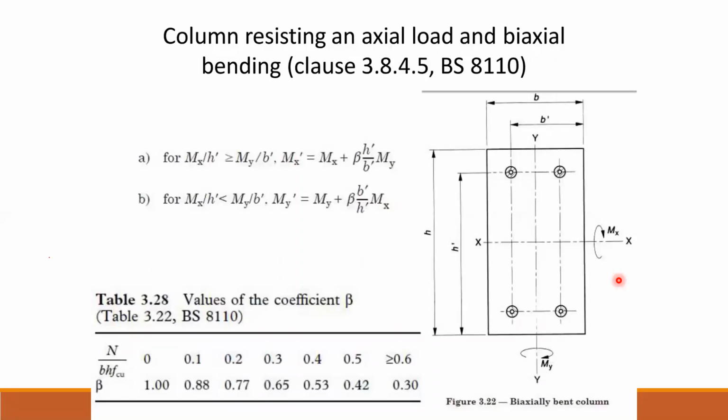Column resistance to axial load and biaxial bending moment. Up to now we have discussed the axial load and the uniaxial bending moment. Hereafter we are going to discuss the biaxial bending moment. For Mx over h', everything is given. Mx is the moment in the plane of yy, that will be referred to as Mx.